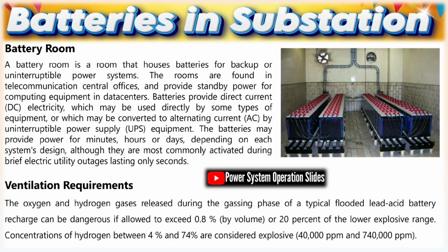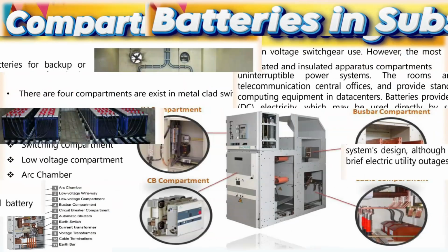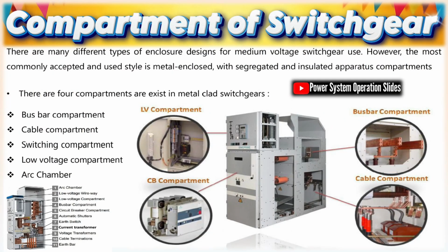PLCC, power line carrier communication. PLCC sends high-frequency signals over transmission lines for control and teleprotection. Line traps and coupling capacitors isolate and direct carrier paths. It serves legacy communication needs between substations.